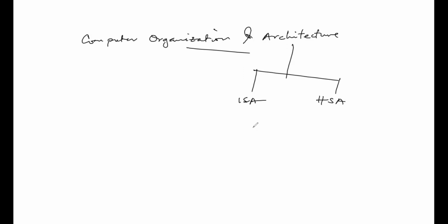Then we went on to talk about two design models for instruction set architecture, the accumulator-based and the general register based instruction set architecture. We put up a schematic in that regard. While the accumulator based has just one register, which is the accumulator, the register based architecture has quite a number of registers, okay?